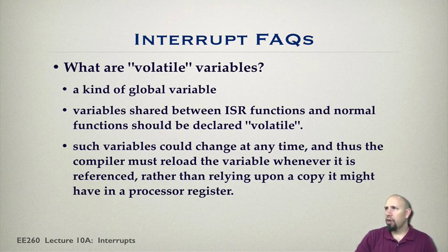So those are some things. It's very common to use volatile variables when you want to pass something into or out of an interrupt service routine.